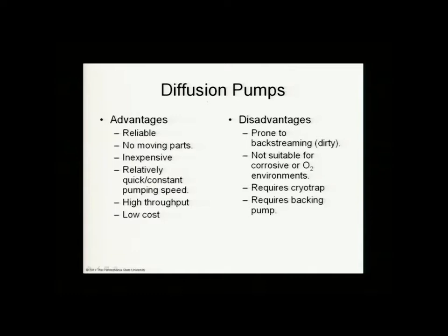Disadvantages, well, this is not surprising. They're prone to backstreaming. And backstreaming, of course, comes from the oil. So that's a pretty obvious problem that you have to watch out for. They're not suitable for corrosive gases or oxygen gases because those entities will react with the oil jet.